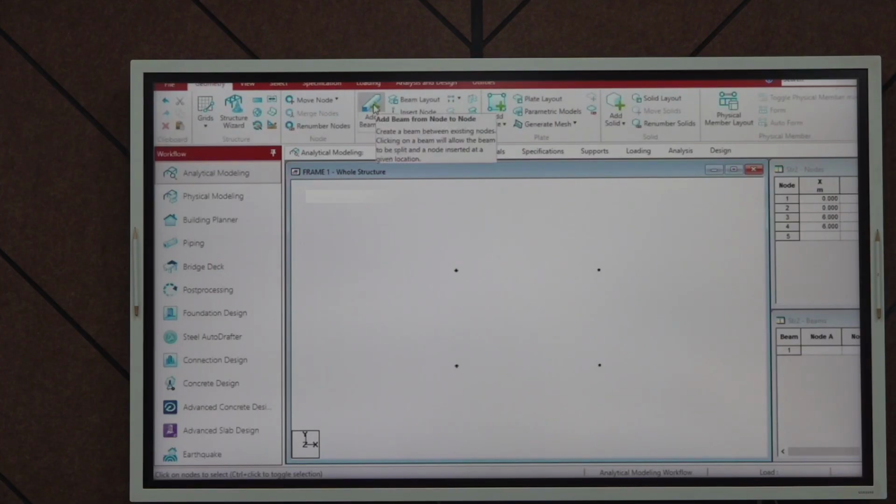Click on geometry. You get the add beam option. Use the command to join 2 nodes to create a beam. I am adding beams to the next part as well, connecting the 2 nodes. It is quite easy. So we have created 2 columns and a beam which forms a frame with a single bay. We shall provide loading now.